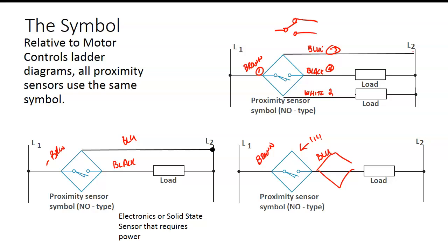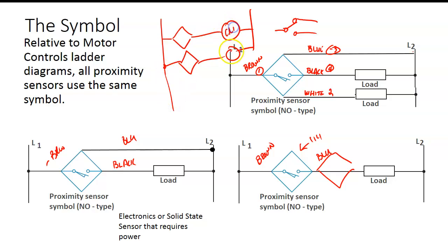So normally, if we had to have multiple sensors, we would just come over here and have this one run a control relay, and then I'd come over here and have another one and run a control relay. That way we would combine them: if we call it CR1 and CR2, then we'd come down here and use contacts to hook in series. Does that make sense? So this would be CR1, CR2, or however many of them. And this way we don't get to a point where sometimes it might work and sometimes it doesn't.